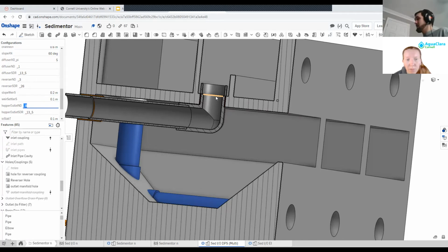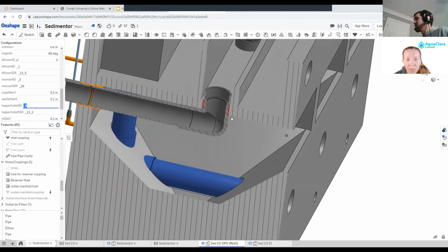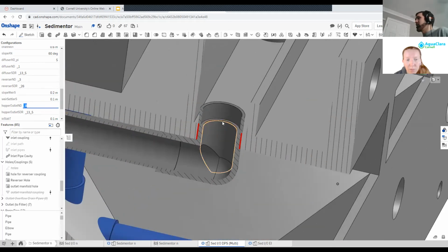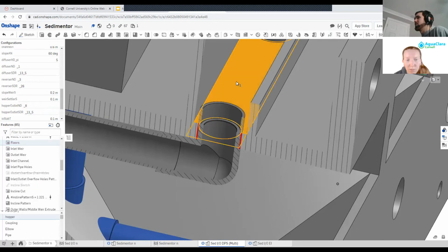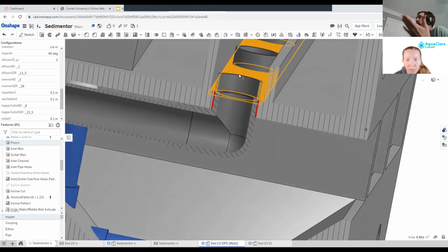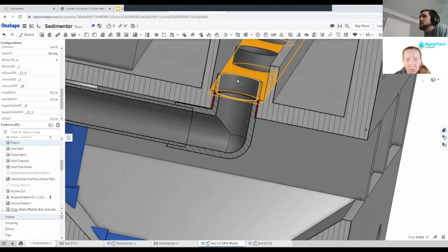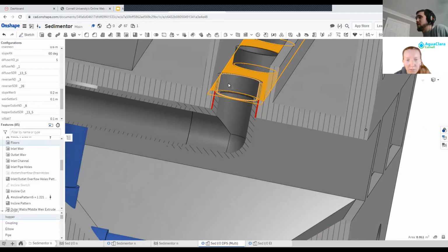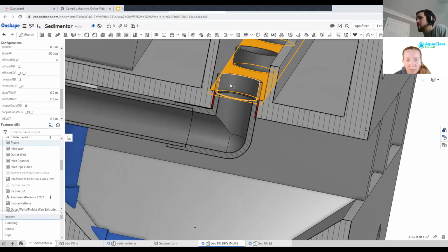However, while pipeline is good at making pipes, couplings, elbows, T's, and crosses, their dimensions aren't always correct. For example, we've imported standard elbow dimensions to try and make this elbow and this top face of the IO line up, but clearly that's not happening. That's because the dimensions of this pipeline elbow don't match standard elbow dimensions. Also, there's no quick way to get the dimensions from this pipeline elbow. We would have to measure them manually and then tell Onshape what they are.